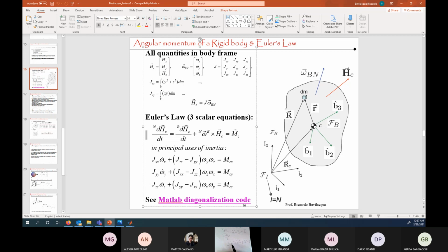All right, so all I'm doing then, dropping all these B and N and all the symbols, is just solving for omega dot, okay? Nothing more than bringing this to the right-hand side. That's why you see that minus omega cross J omega plus T, and inverting J. And we know we can invert J because of the properties that we've seen before.